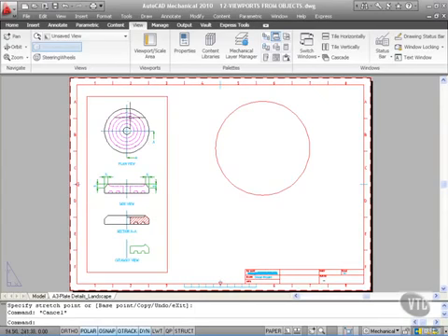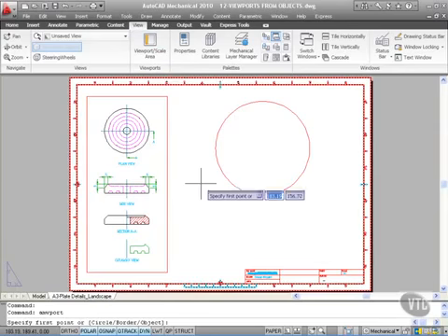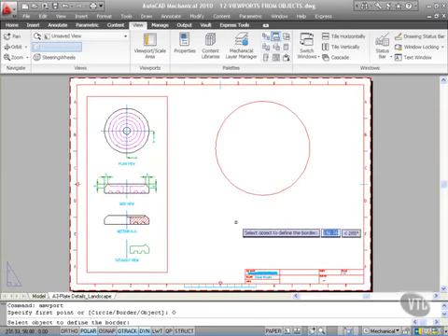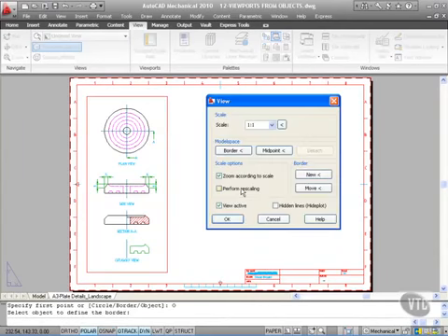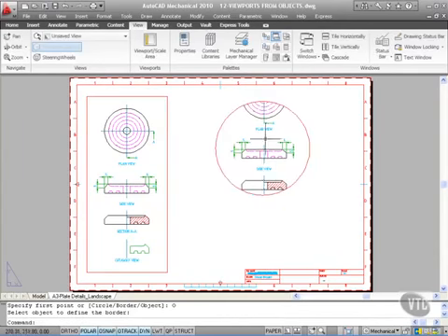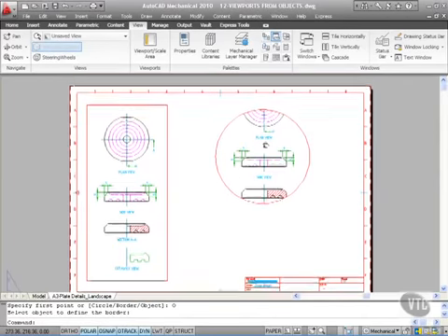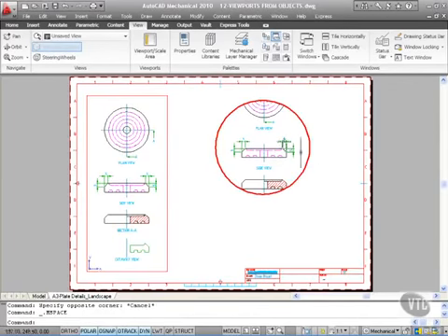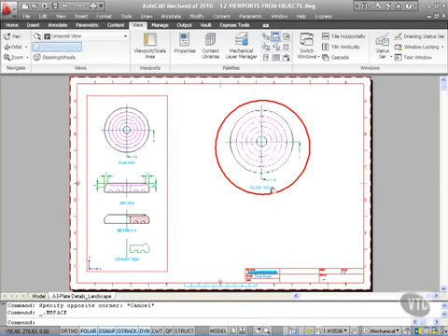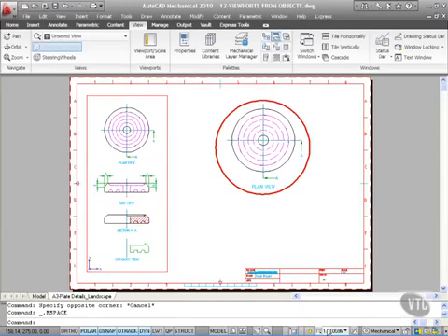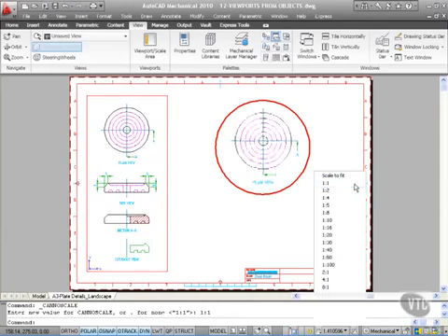Now you'll notice my plan view is circular. So if I now convert this circle to a viewport by clicking on Viewport Scale Area, right click, Object, and clicking on the circle, it becomes a viewport. I'm going to leave the scale at 1:1 and OK it, and then just pan downwards a little bit. Now you'll notice I'm panning the drawing because I need to double click inside the viewport first to activate it, then pan. So I'll pan down like so, there's my plan view, and I want that to be 1:1, let's say, so I go Viewport Scale, 1:1.